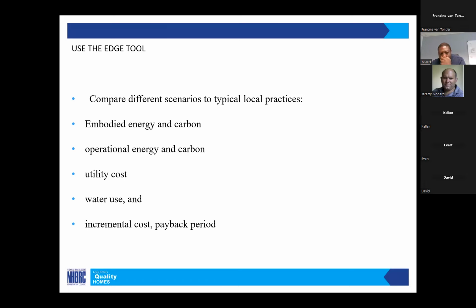So if you use the Edge tool, it will give you the barometer, and you go to Agrement, or you use your standards, or you do your rational assessment, because there are means of compliance. One is your standard. Your rational design is the reasoning by the engineer or competent person in relation to the standard. And you have rational assessment, whereby you totally don't know the characteristics of the material, but when you test it, it gives you less than you would have expected in conventional. So we call it the rational assessment.